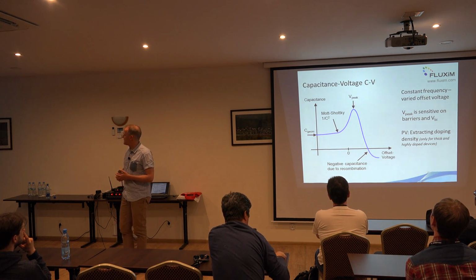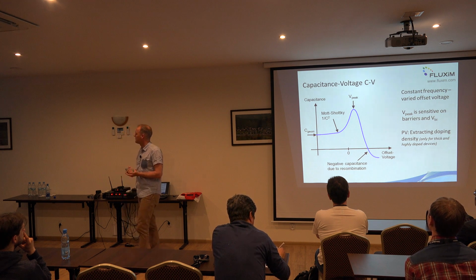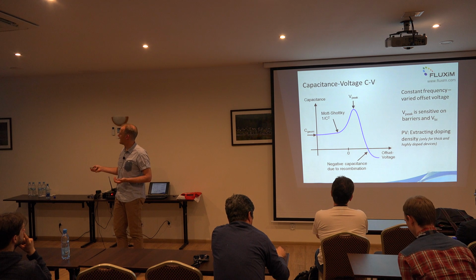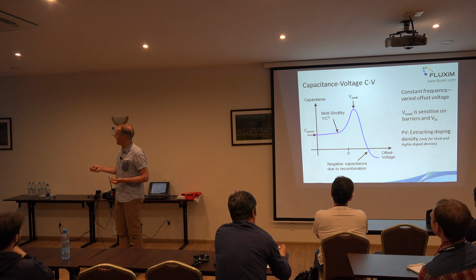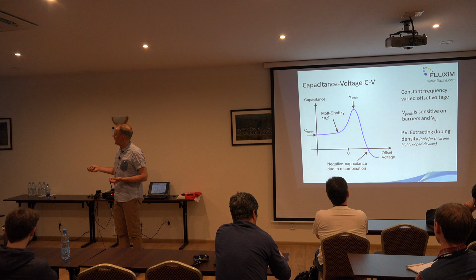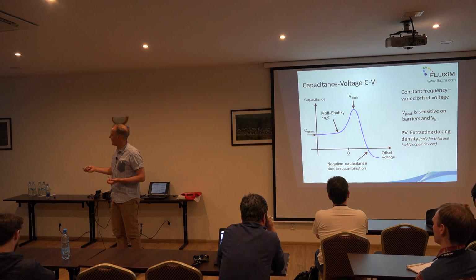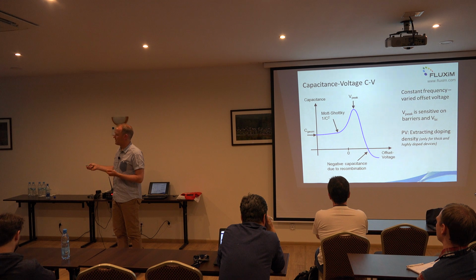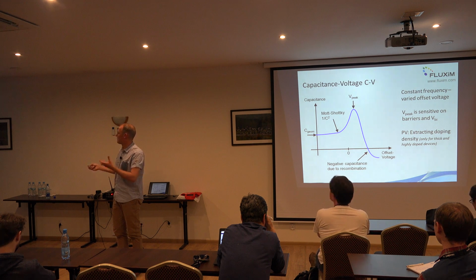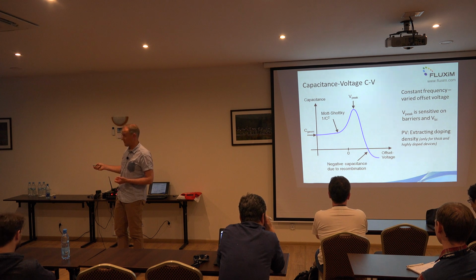Now the capacitance voltage method is well known, for instance, for Mott-Schottky analysis. There I already mentioned that in reverse bias you expect geometrical capacitance, and then if the applied voltage overcomes the built-in potential, you start injection, and then you have charge penetration, which leads to an effective increase of capacitance.